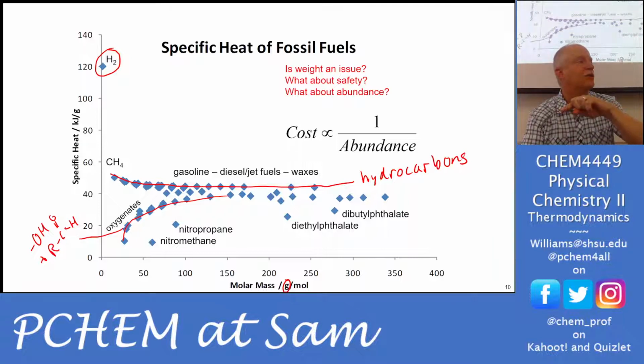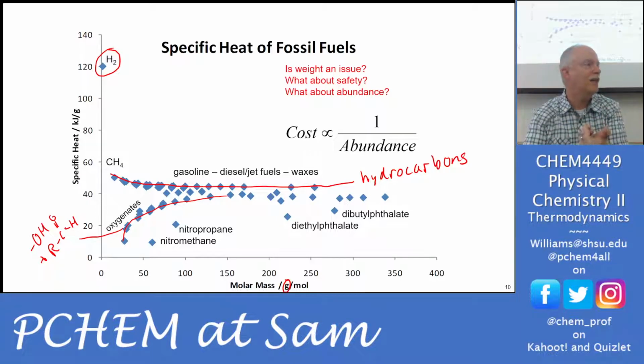So for high current electricity, we can move electrons at enormous currents, but we can't move protons that fast. And so the current limiting step in all of these fuel cells is how fast you can move the ions. You can move the electrons incredibly fast, but moving the ions is the thing that limits our power. So we can make hydrogen fuel cells for low current demand, but it's the high current stuff like transportation that really is a problem. So they want to try to combine it with supercapacitors that can hold an enormous amount of electrical charge. They can deliver the high current, high torque situation for accelerating. But then we charge them up with the fuel cell.